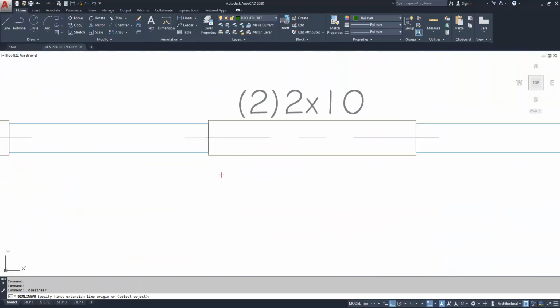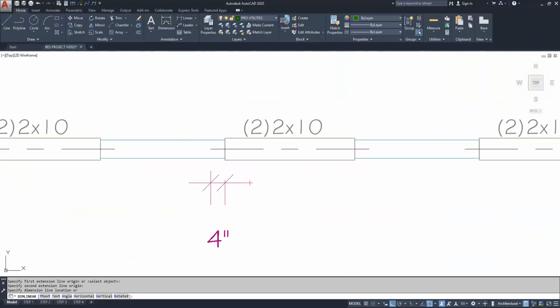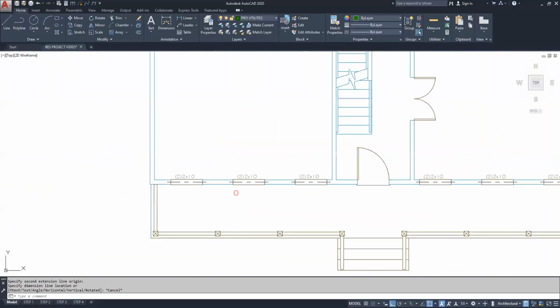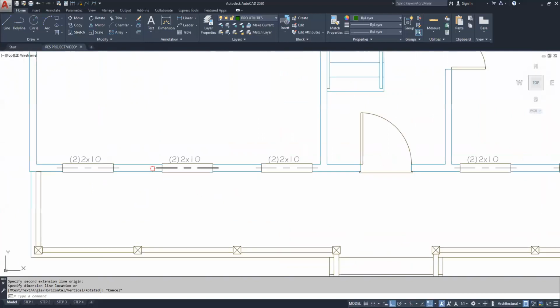Now the distance past the window is about 4 inches. You don't have to measure this, especially by manual drafting, hand drafting. You could just kind of eyeball it, but it needs to go past the opening. Why? Because we're going to be resting on a wood post. We don't have to exactly put a wood post everywhere. It's kind of understood, but you do have to make sure that the head is longer because it has to rest on the trim and the king stud. Or it rests on the trim and goes to the side of the king stud.